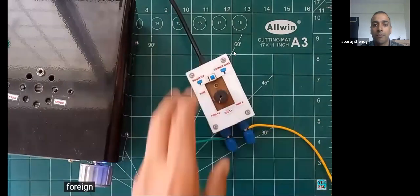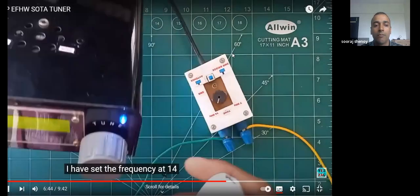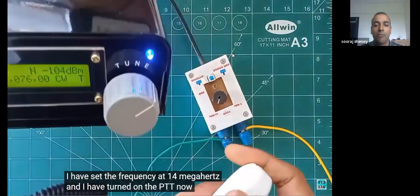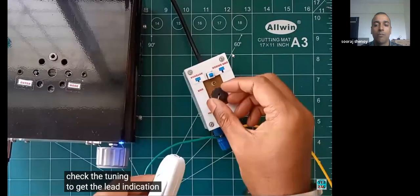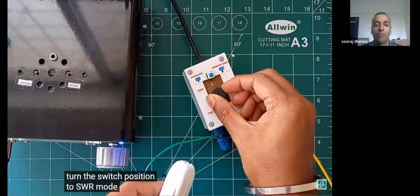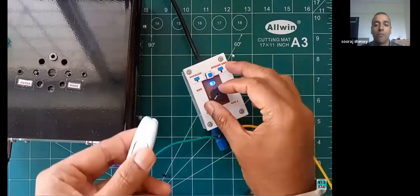Now let's start. I have set the frequency at 14 MHz and I have turned on the PTT. Now let's check the tuning. To get the LED indication, we need to turn the switch position to SWR mode. You can see the LED is glowing.